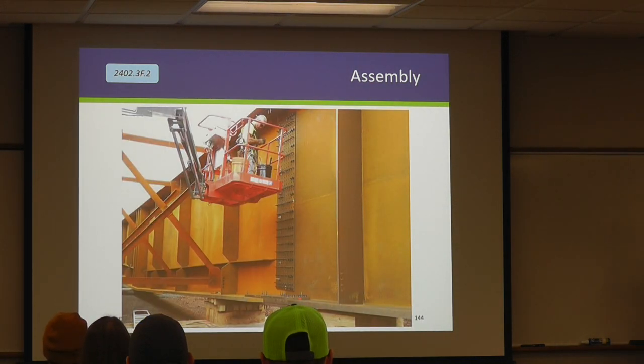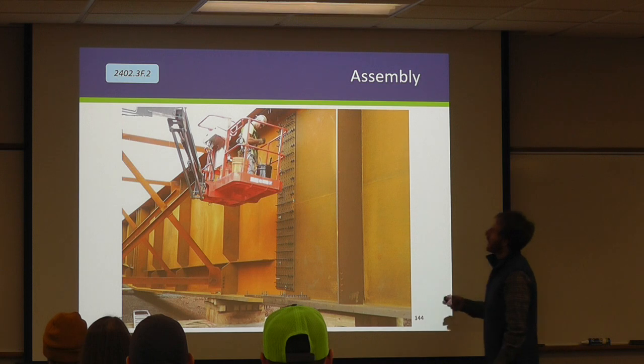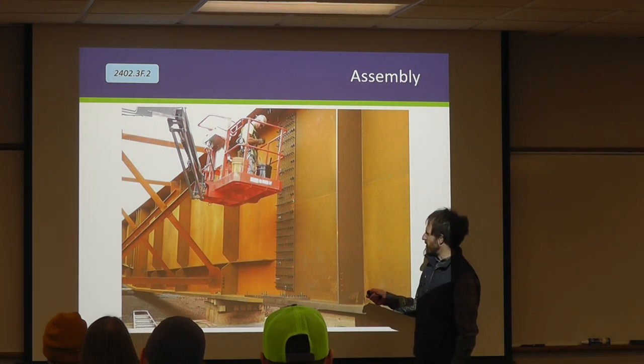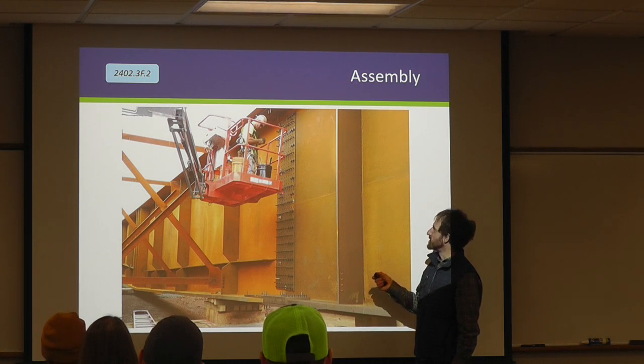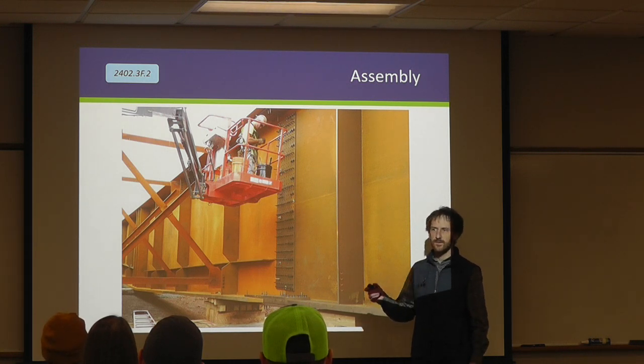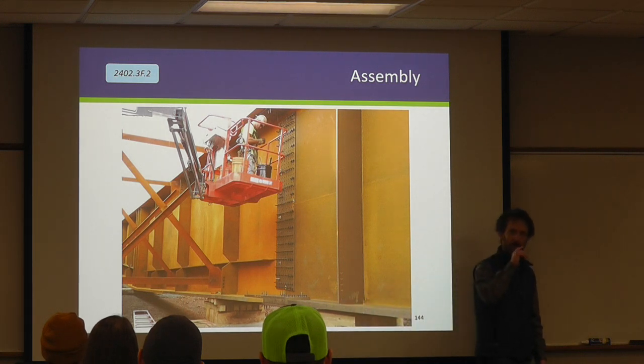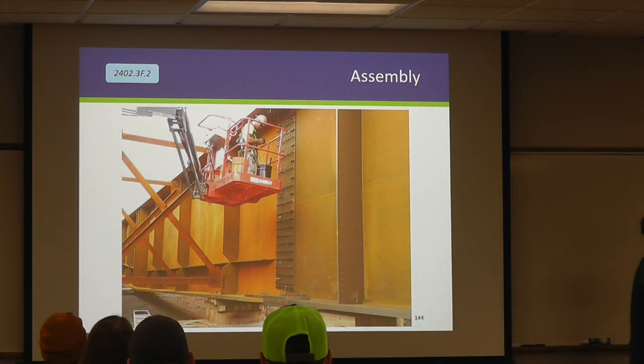This is a ground splice, but the theory is still the same. Maybe a little bit hard to see here, but more or less what they've got going on is every other line is pins and every other line is bolts. So I would say this is well distributed, right? Probably overdid it on pins and honestly could have gotten a little less. That's fine. We're not gonna tell them.